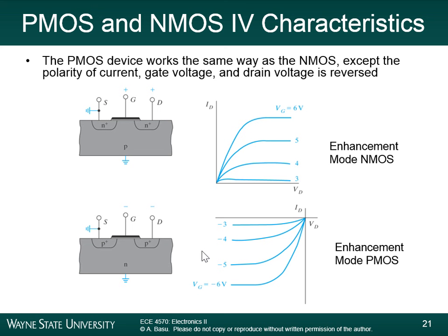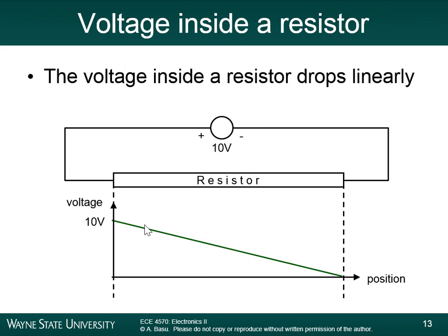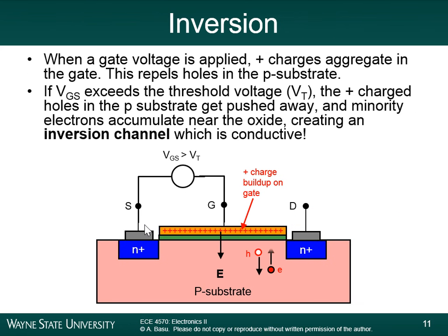All right. So you might be wondering, well, that doesn't really make any sense. Going back to this graph here, how can you possibly have an inversion channel if you don't apply any voltage to the gate? Well, the reason for this is more complex. But I will say that the way that it works is that you do something called ion implantation. The ion implantation can actually create some negative charges in there, so that you actually have a conductive channel even at zero bias.